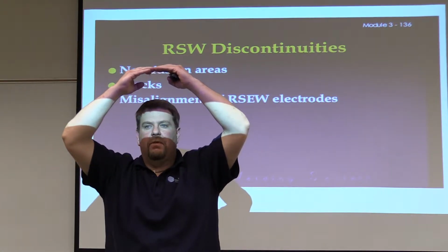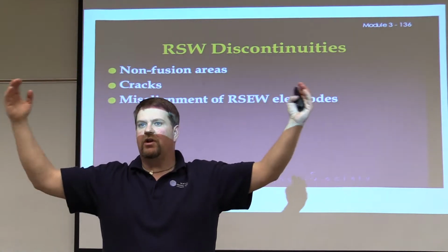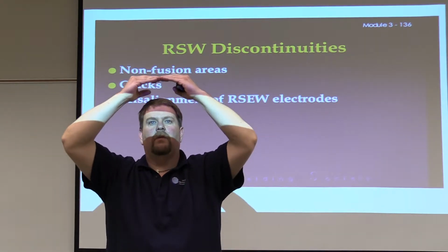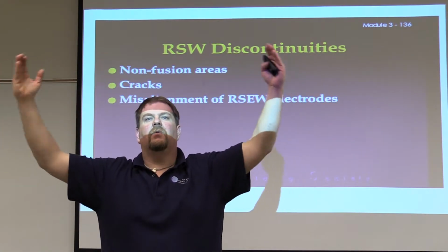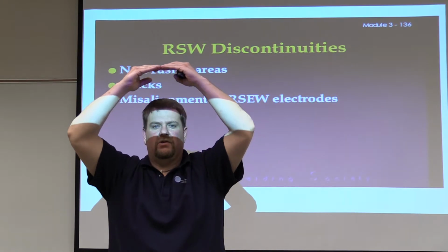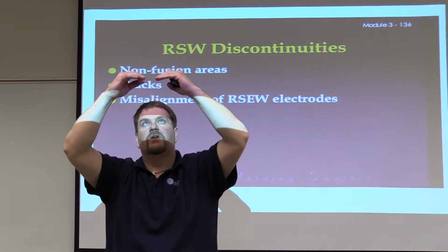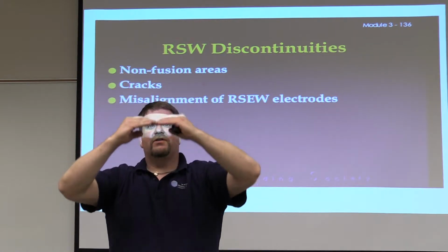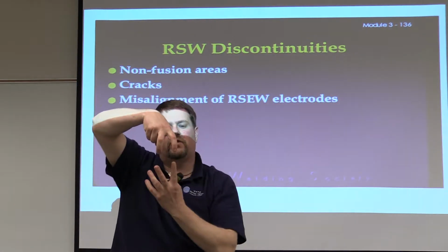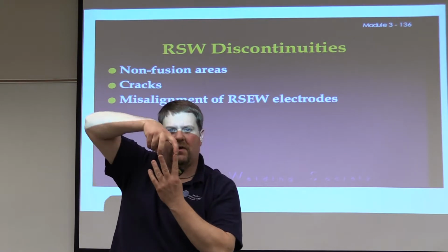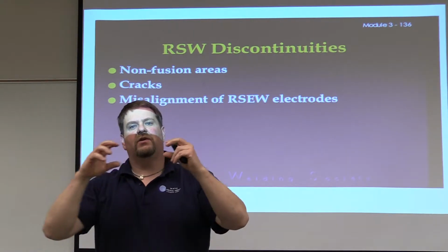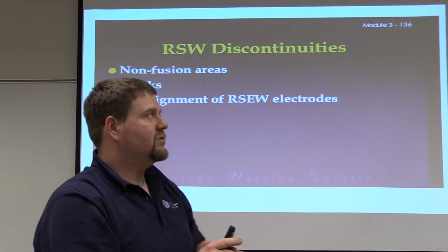Okay, same thing as seam pipe or anything else. It's usually not drawn over a mandrel in one piece. It's a piece of plate that they run through a set of rollers and they get it into a round shape. Okay, then they weld the top in a flash pattern or something else. Well, in a seam weld, what they can do is take this seam and they can run two parallel rollers just like this up and down that, and it creates that friction between them and bonds those two together in that butt joint. All right.